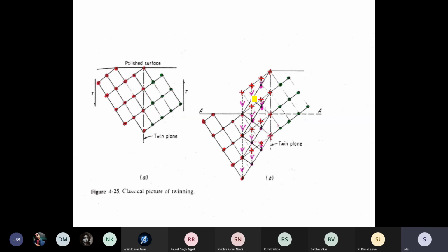But in case of twin, every single atom in the twin region moves in a particular direction by a fraction of a lattice constant. This fraction is also fixed depending upon the position of the atom with respect to the twin plane. Imagine billions and billions of atoms in the twin region move by a fraction of an angstrom in the particular crystallographic direction instantly. And this is the beauty of material science or metallurgical engineering.